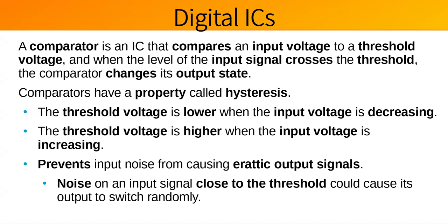So the hysteresis circuit is there to avoid noise on the input signal. But then I think a little bit later, we'll find out how we actually inject noise to get a half of an LSB out of the thing, which still I have trouble wrapping my mind around, but it works.